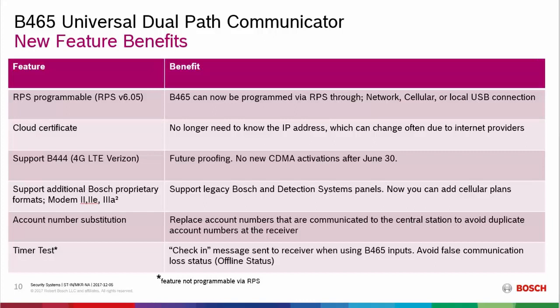So the first one, RPS programmable. When we first launched the 465, the way you programmed it, I'm sure a lot of you are familiar with, is the TerraTerm interface. It's not the easiest to use. You can't create templates in the TerraTerm interface, and it can be kind of a pain. So now with the newer version of the 465, with version 2.0 firmware and version 6.05 RPS, you can program the 465 through RPS remotely through network, cellular, or a local USB connection.